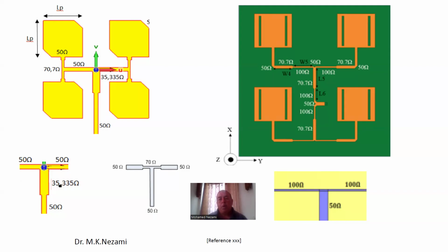Okay, so that's why a lot of times we need to get away from these small lines, and they're fragile too, so you could peel them off so easily. So a lot of times they don't use this, but let's see that this individual here chose to do this. You get this here doing the first split, equal split. Okay, so you got 100 ohm in parallel with 100 ohm, that's 50 ohm, and you got feed 50, so you're done here. You don't need to use transformers.